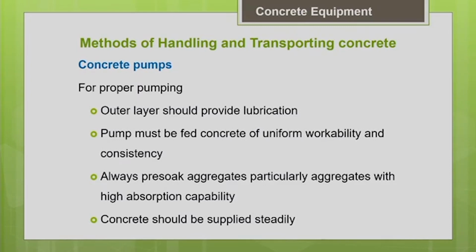So what are the other guidelines? Let us see. As I told you, the important thing is that before pumping your actual batch of concrete, you have to do some lubrication. That lubrication will facilitate easy flow of your concrete through the pipeline. And we should feed the concrete pump with uniform consistency and uniform workability. That is very important so that you can have a uniform flow of concrete to the pipeline.